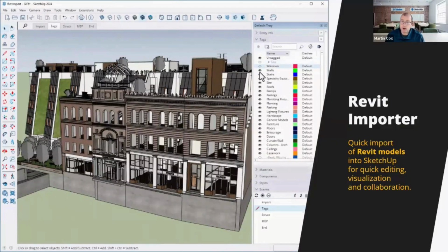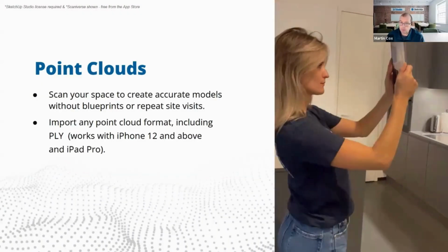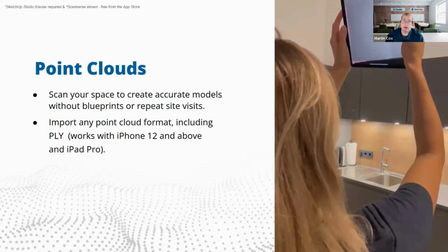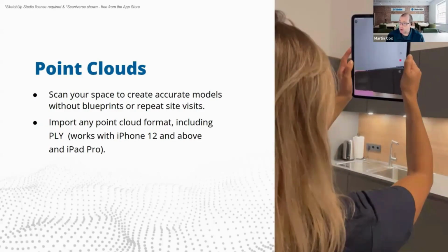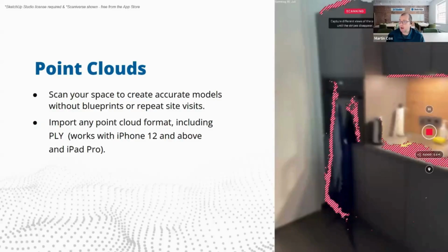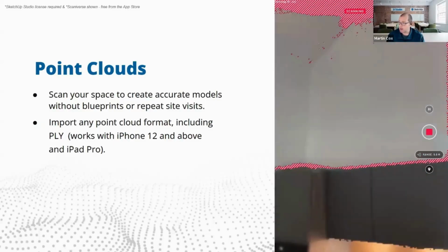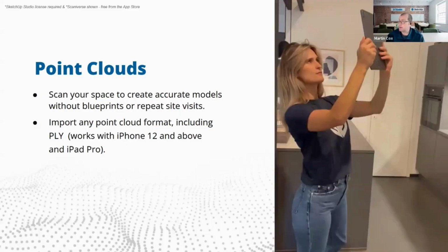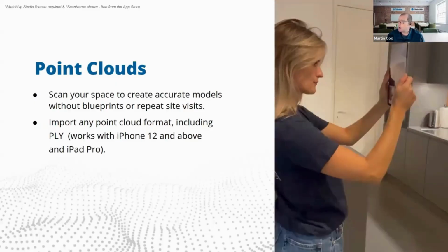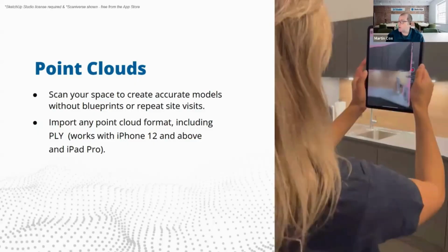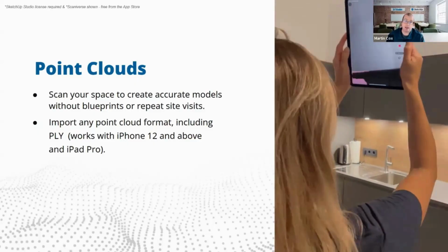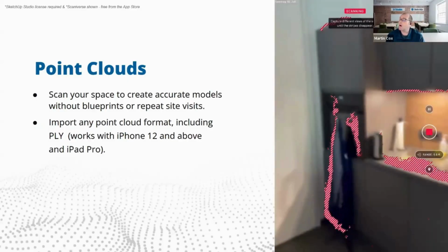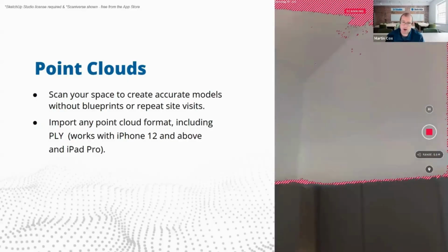Also point clouds. Point clouds are an amazing way to get working when bringing in your model. You can scan your space to get those models, and you can work with that point cloud directly inside SketchUp. In this example, we're scanning using an iPad. iPads and iPhones have a built-in LiDAR scanner, and you can scan smaller spaces and smaller models using just the iPad.